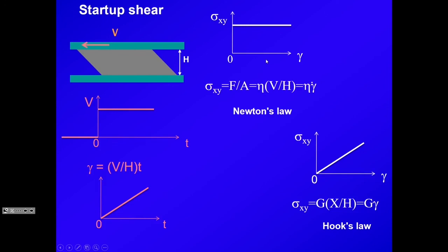No, quite the opposite. I mean the following. You can have a piece of viscoelastic polymer melt, for example, whose tau is 100 seconds, whose viscosity is, of course, huge. Such a material with 100 second tau, you have no trouble going with your time resolution.